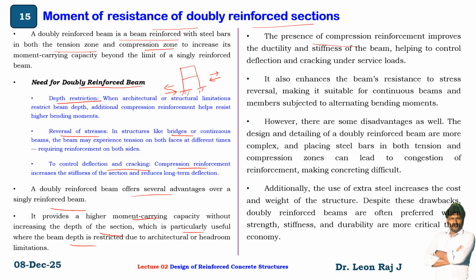The presence of compression reinforcement improves ductility and stiffness of the beam, helping the control of deflection and cracking under service loads. It also enhances the beam's resistance to stress reversal. So I told what stress reversal is. So it has the resistance for stress reversal.